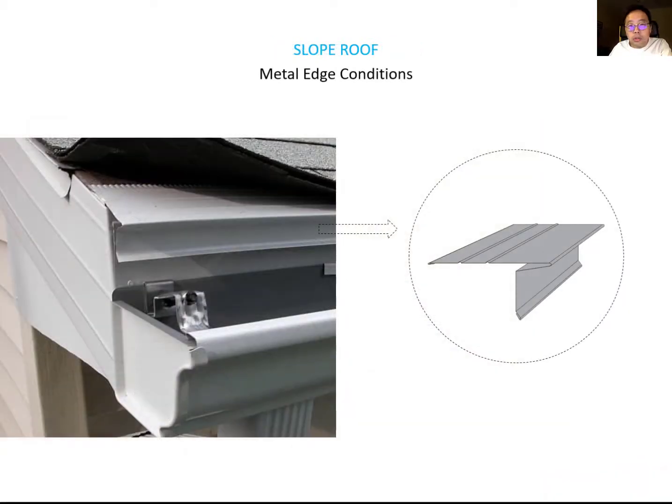For the moderate roof or steep roof, it probably requires flashing at the roof edge, and this flashing laps up the waterproofing membrane. You can see this edge and the waterproofing membrane lapping up to protect this corner.